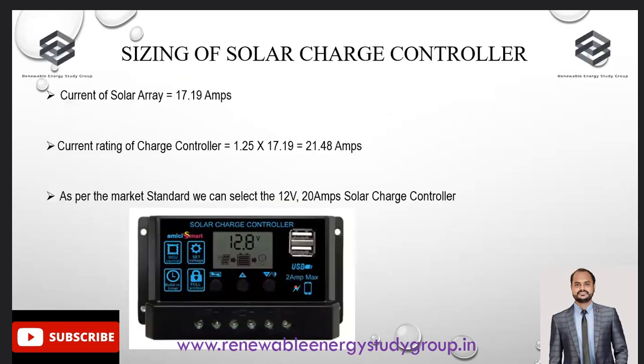Once we have connected the panels in series and parallel combination, then we have to select the charge controller for the solar system. For selection of any charge controller for the DC system, we must know what current is flowing from the array, that is the output current collected from the overall solar array, which is 17.19 ampere. So we multiply this value by a safety factor of 1.25 and we get 21.48 ampere. This is, on an average, the charge controller rating we have to select, or whichever is feasibly available in the market.